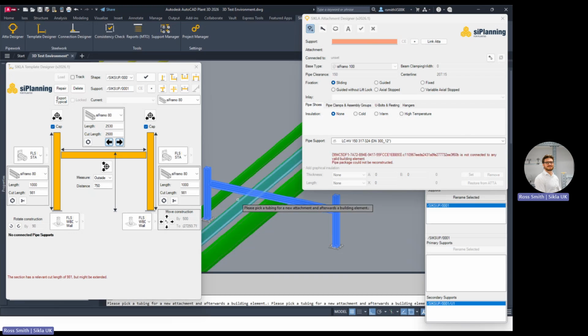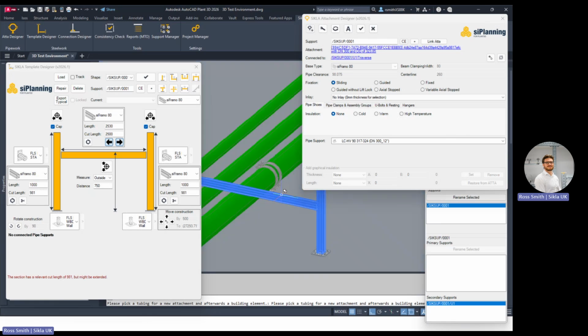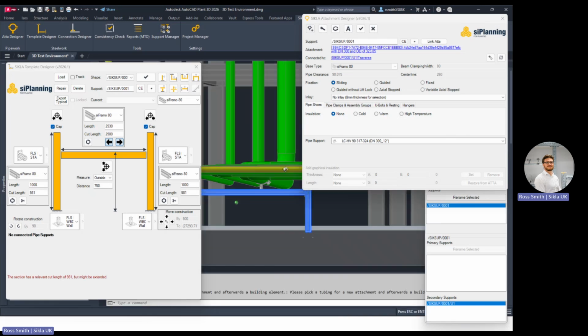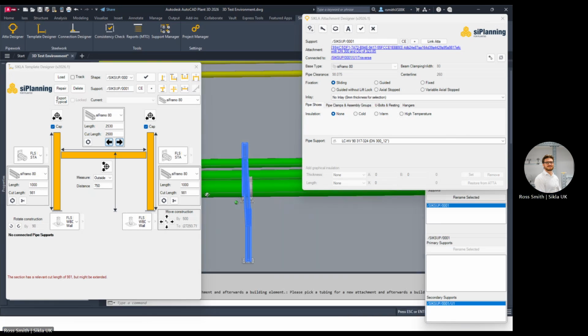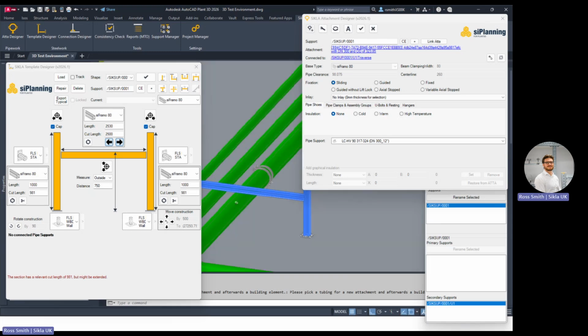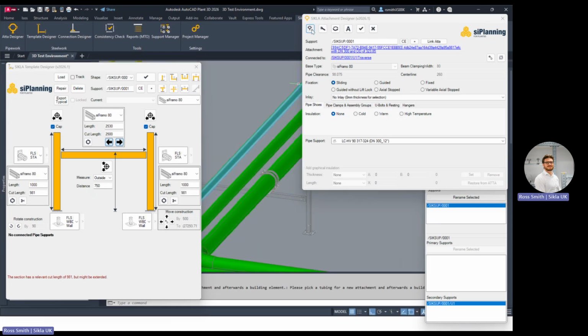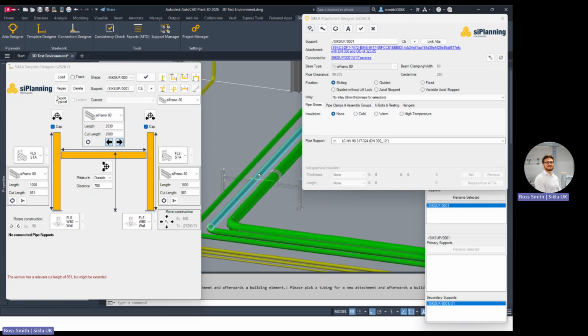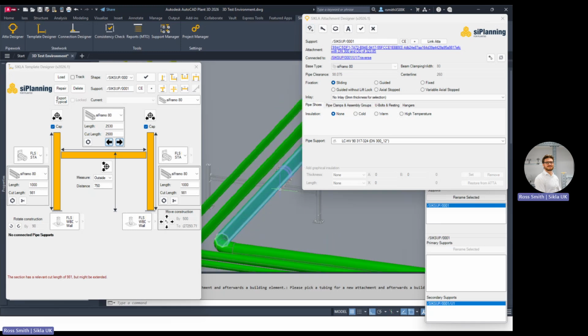And then secondarily, subsequent to that, I'll want to associate it with the crossbar. So similarly, I'll hover over, left click to click the crossbar, and there we have a primary support, which is in line and associated with the piping. I'll continue to do this. The tool turns itself off at the moment as a default because it is easier to then reactivate rather than accidentally create more piping supports. So I'm going to create another one as a default, leaving all the settings as they are.